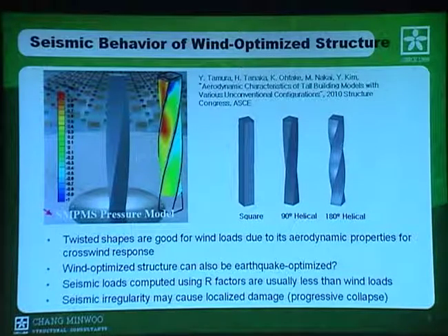However, the wind optimized structure can also be earthquake optimized. This is the main concern of our research project. In tall buildings, seismic forces such as story shear and overturning moment are less than the wind forces. Thus, member design is usually governed by wind loads.